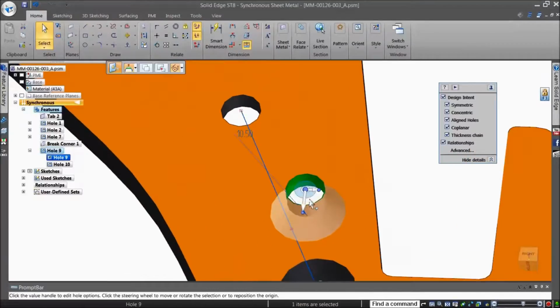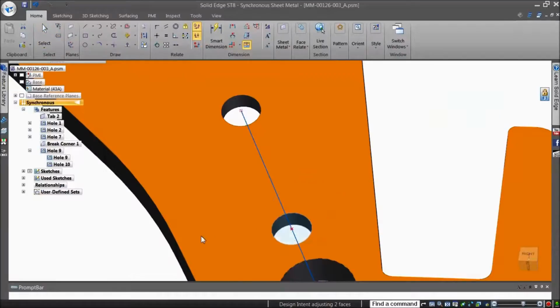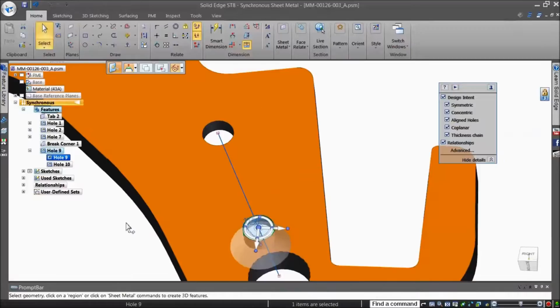Select the hole and pick the tool plane on the steering wheel. This is the transparent disc at the center of the steering wheel, allowing you to move the hole freely on the plane rather than along an axis. You can select the midpoint if that is your final location, or select a point created on the line. You can also use dimensions for precise control.